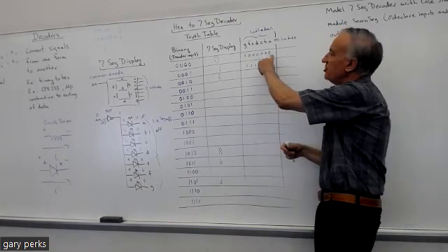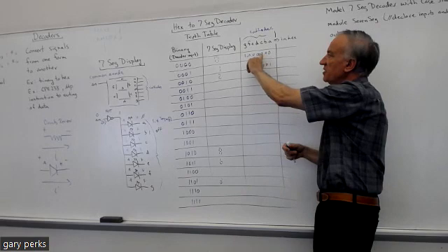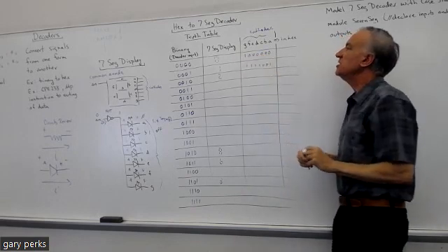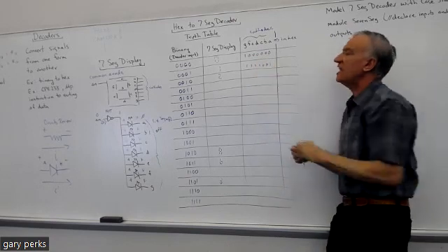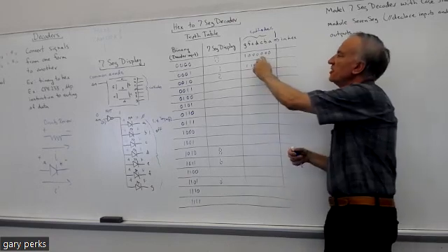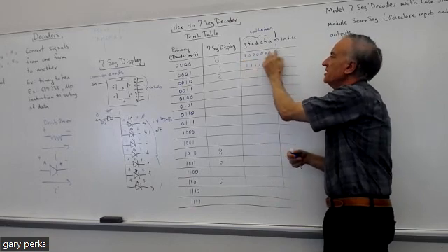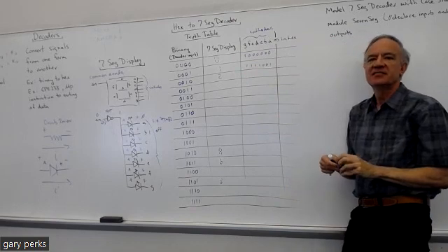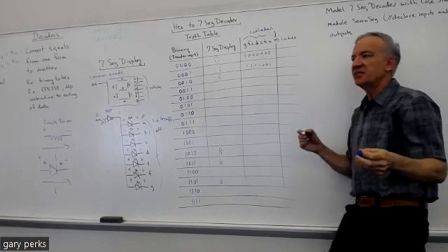And that's to show these 7 cathode bits, instead of as binary ones and zeros, as hex. So if I want to show 1 0 0 0 0 0 0 in binary as hex, how can I do it quickly without going through base 10? You did it at the beginning of your class. Yeah, the grouping, right?